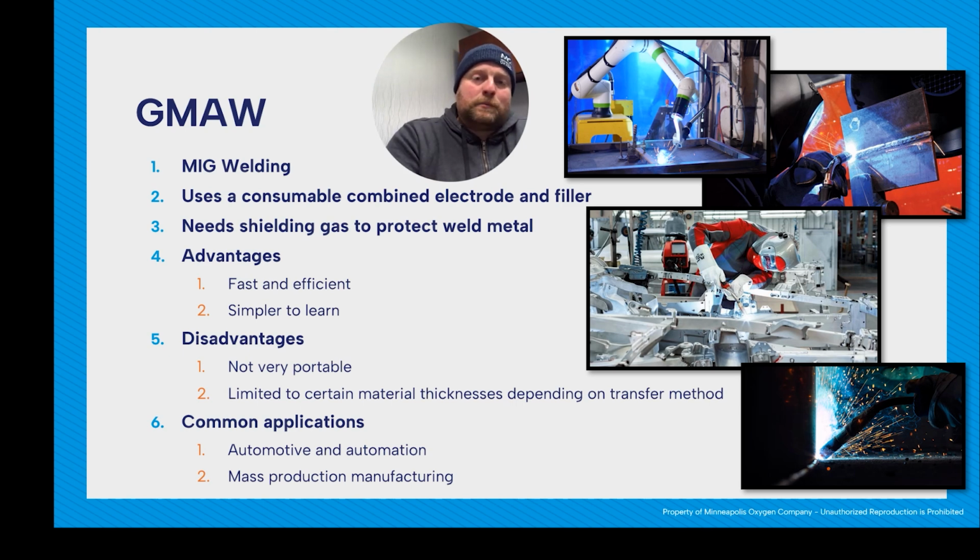In SMAW, you have the flux. The flux melts and creates a shielding gas to prevent atmosphere from getting into your weld. And also, the flux helps to clean out any contamination in your weld. So it's really great if you have something dirty. You should always be prepping your material well, but we can't always do that. So if you have dirtier metal, stick is great because that flux cleans everything out.